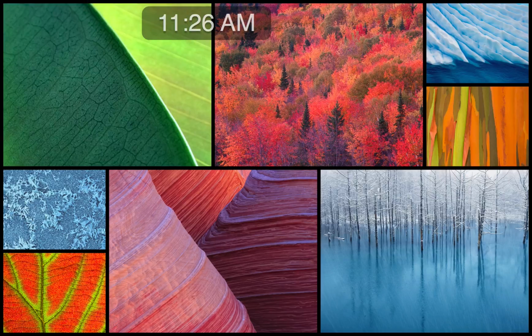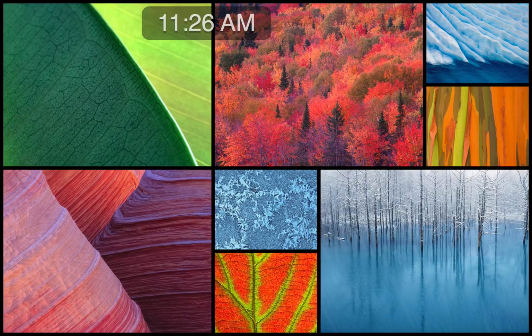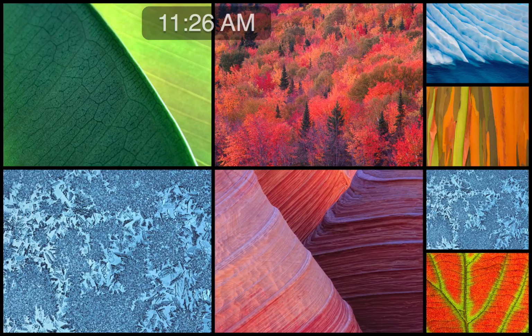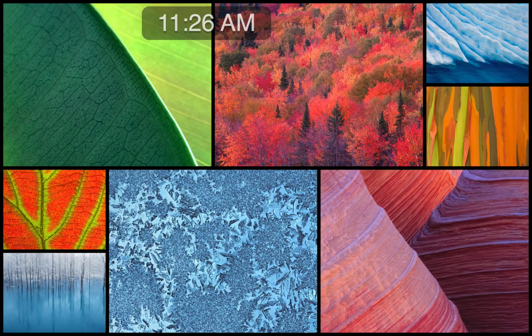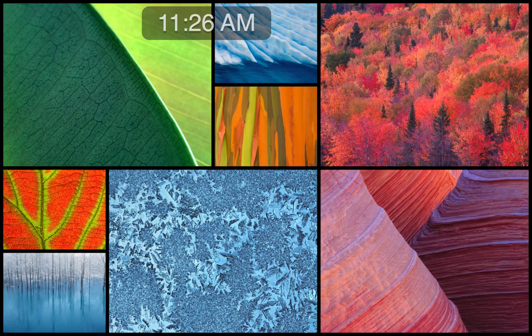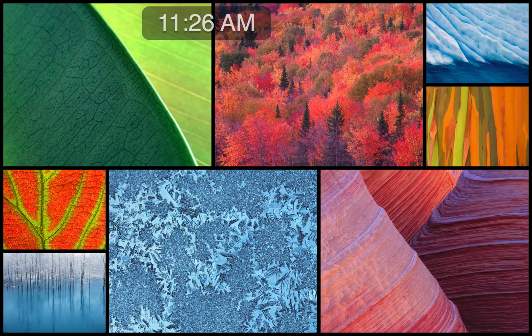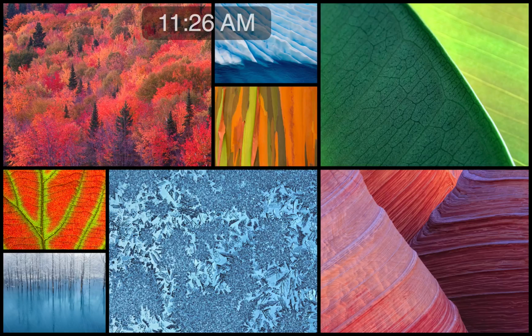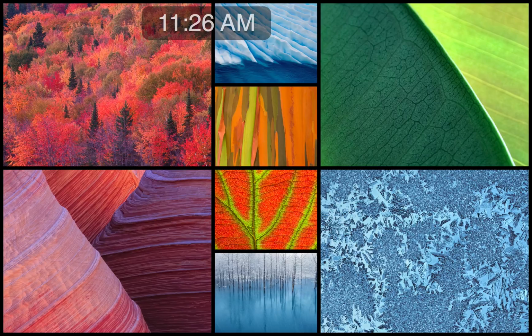Array. Array. 5 of them. 2 feet apart. Okay, there's my studs. Oops, I needed a 6th one. Okay? So again, my wall's looking okay. What do I need to do now? I'm gonna leave my reference planes for now, but yeah, I should delete those. There's way too many. Yes.